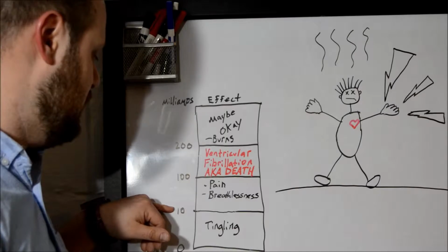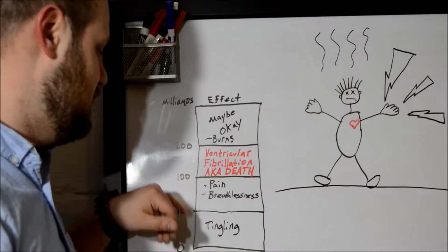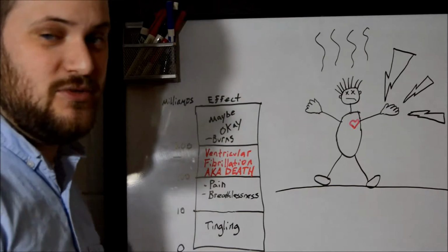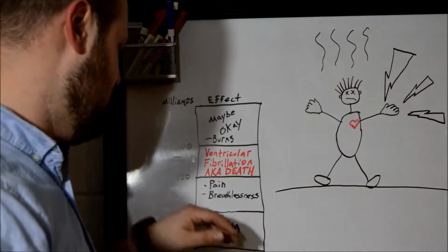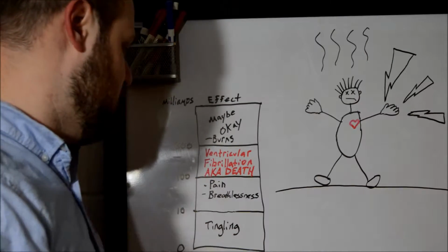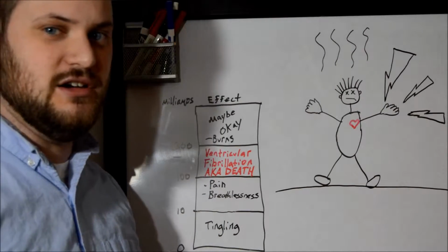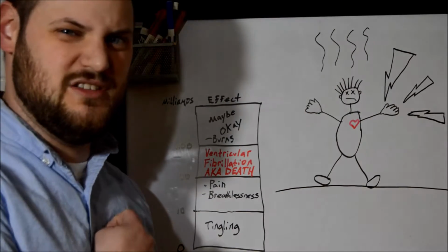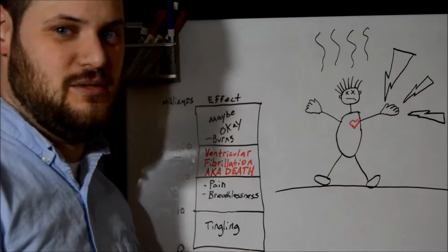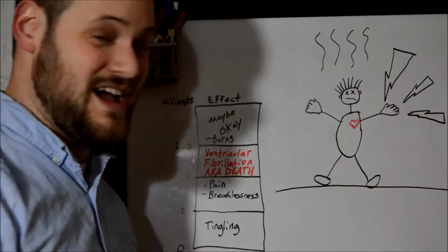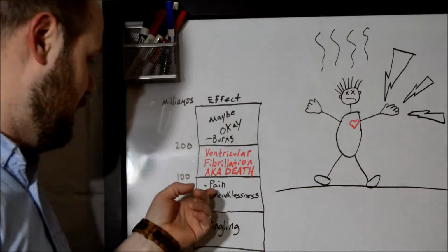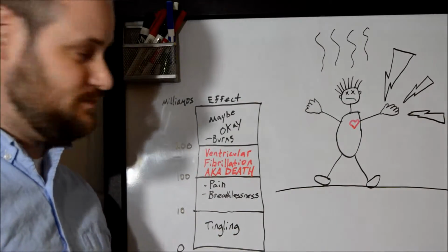As we move up here, anywhere from 10 to 100 milliamps, say 50 milliamps, somewhere in there, you're going to have pain and breathlessness. We're talking about a much more severe shock here. A shock like this feels like somebody just kicked you in the chest. Maybe some of you have had this kind of shock. I sure hope not. But that's the next level.